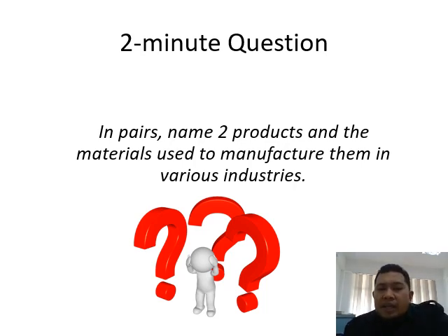As for the mechanical pencil, previously you had a wood pencil with graphite inside it. That one is the most traditional one. And then you can have a mechanical pencil. When you have a mechanical pencil, you have to use a spring, a cover, and a gripper which is made from alpha gel, and then you have to use different kinds of plastic. For example, the outer case should be made from polycarbonate, which has higher toughness and higher tensile strength, fatigue strength, and also bending strength.